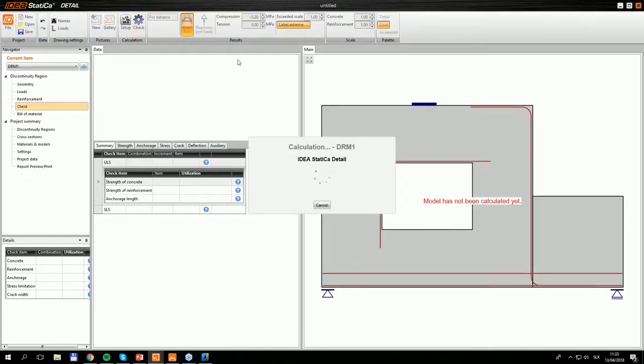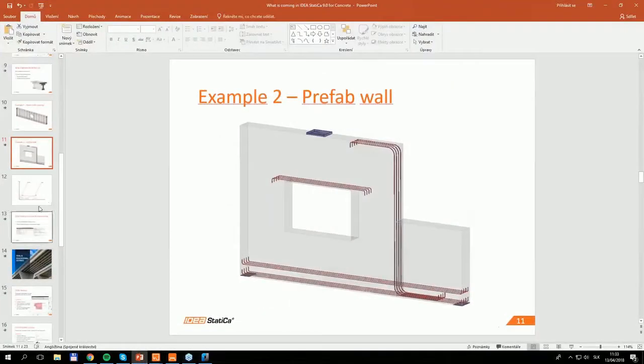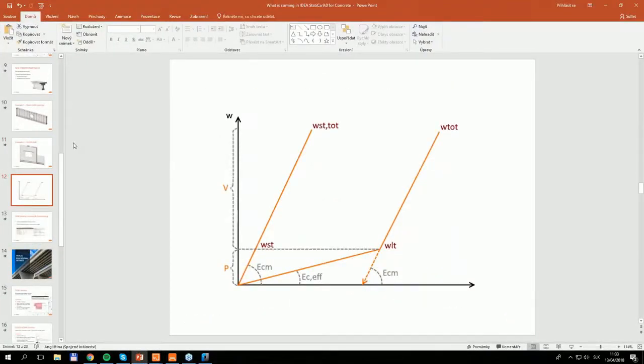I will run the calculation, and I don't want to repeat my colleague, so I'll try to explain something else, because as you will see, we have actually more models implemented as of now, because we can cover both short-term and long-term effects in the SLS calculation. What is it about? The first model is this one, this orange line, and actually we apply the permanent load and the short-term elastic modulus. Then we receive the crack width or the deflection for a short-term effects.